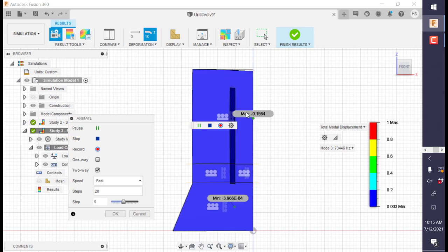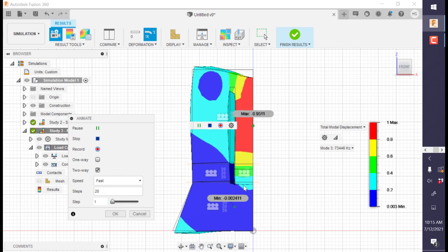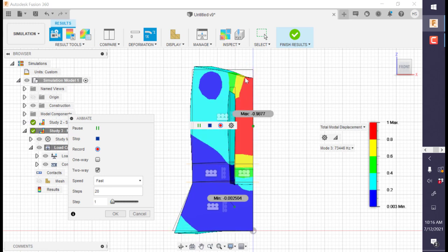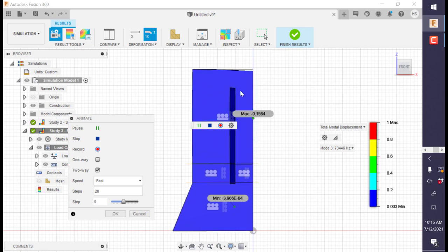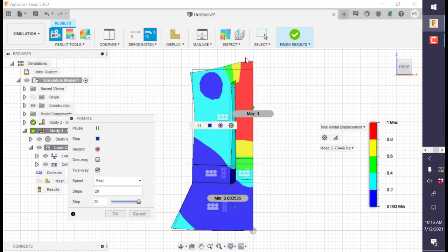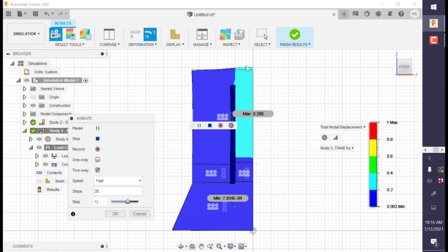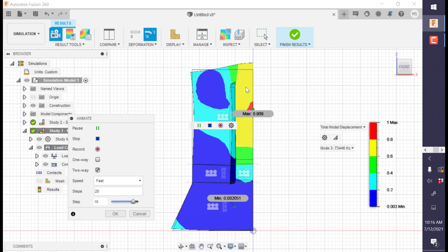at 73 kilohertz, where we have the center bolt apparently pinned at the bottom here. So there's very little displacement here, but it's simulating a free displacement at the top. So there's a pin condition here and almost a free displacement or maximum displacement at the edge. This is another resonant mode, which also will be found in our impedance analysis.